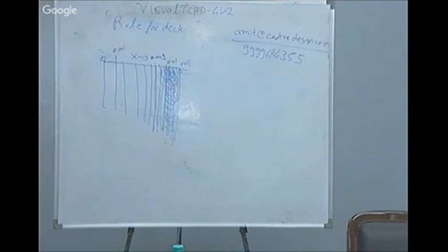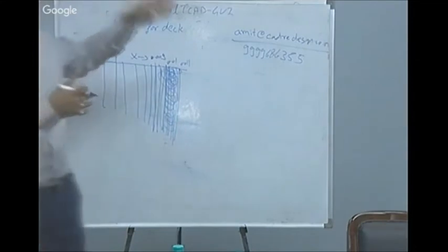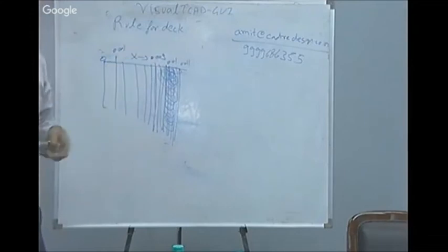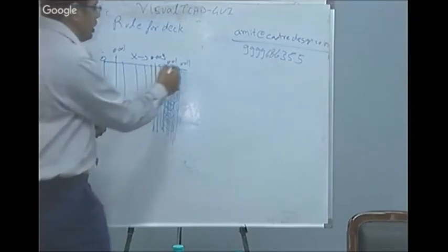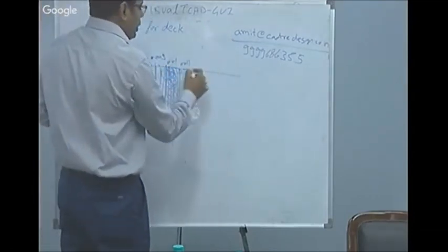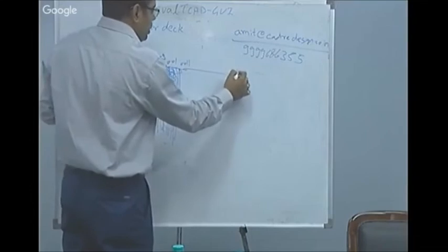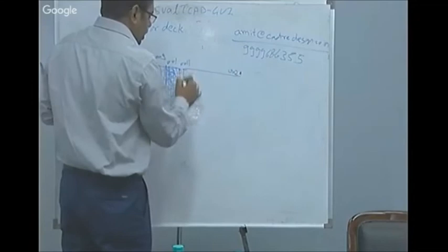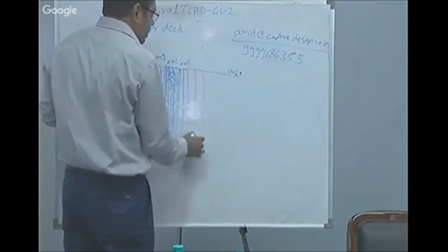That's why we give a high number of n spaces. We want to increase the number of mesh points. Then n width 20. So if we have 20, the number of spacing is 20. So it means it is 21 points. Here the number of lines are 20.